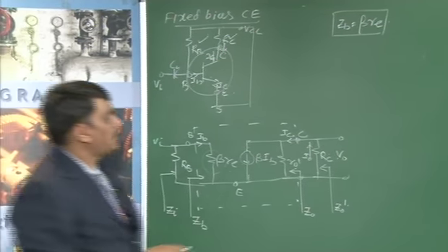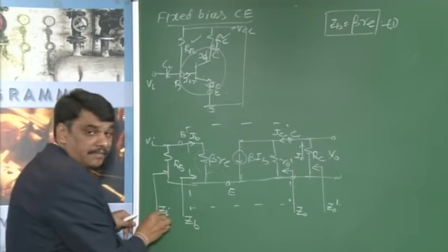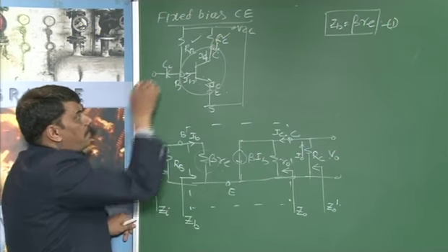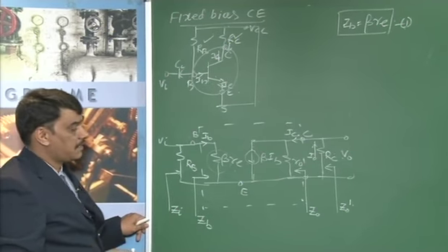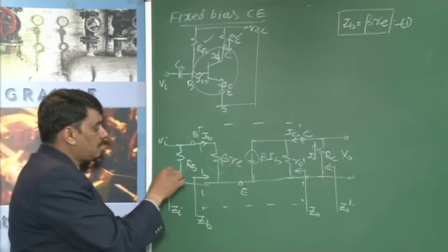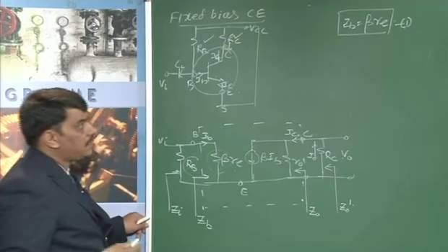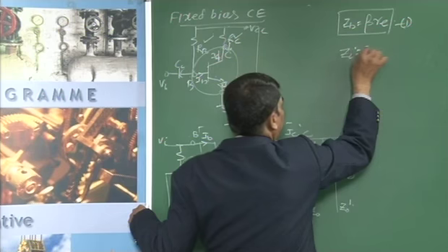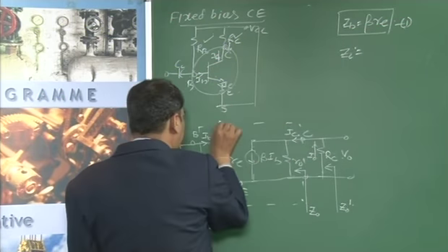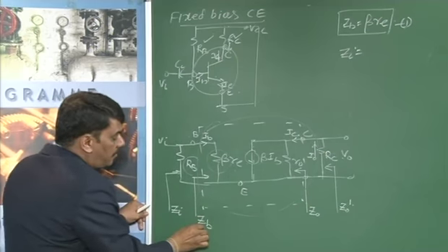That is one of the important expressions. You have to determine Zi, which means when the circuit is biased with a fixed bias or a voltage divider or any biasing circuit, you have to determine the input impedance by considering the resistance RB. Then Zi is nothing but a parallel combination, where the entire transistor is replaced with its input resistance ZB.